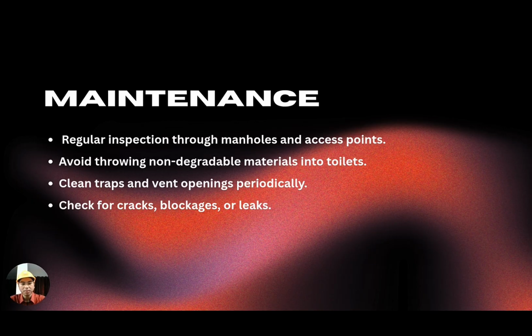Soil pipes must be regularly inspected through manholes and access points. Users must also avoid throwing non-degradable materials into toilets. Traps and vent openings must be cleaned periodically. Cracks, blockage, or leaks must also be checked periodically.